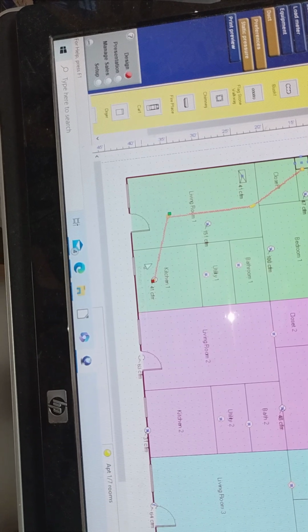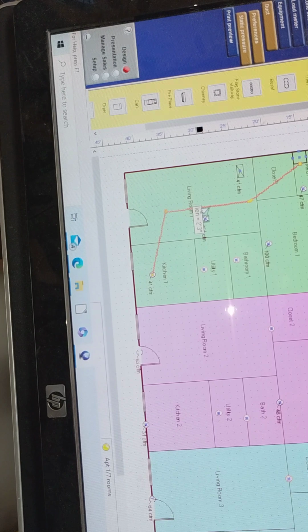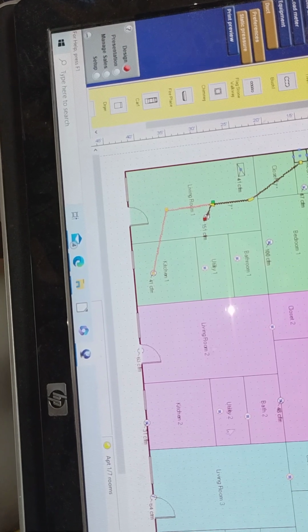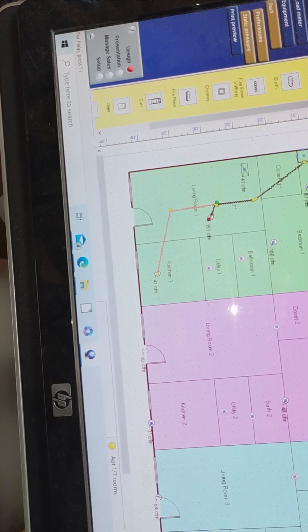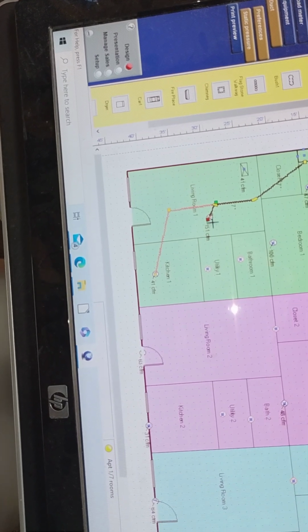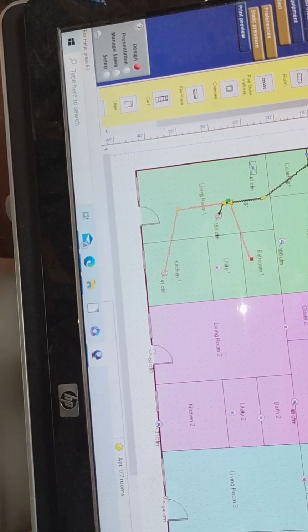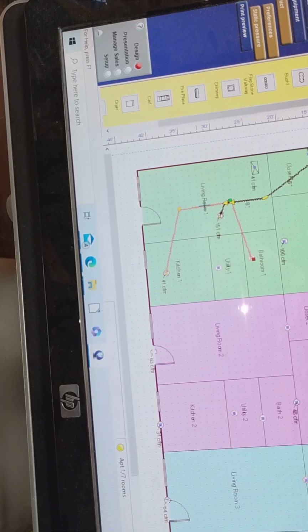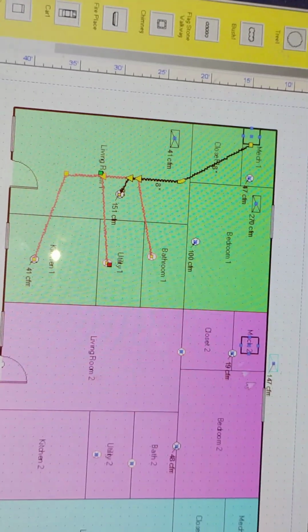And once we connect it, it will begin calculating out what size of duct we need. I don't know why this one on the end hasn't, but again, I've got time after this video to address that. Probably just don't have it dragged completely in the middle of the grill, but we'll take care of that in a minute.